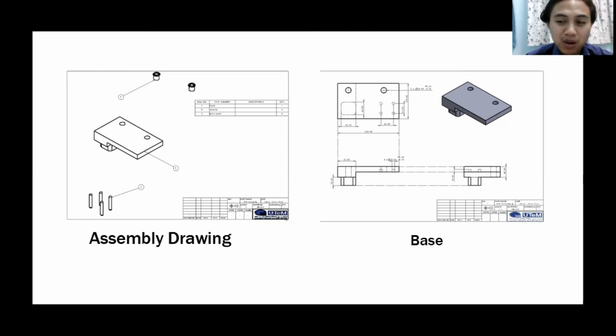This Poka-yoke concept in the design reduces or prevents errors associated with misalignment of the part. Selection of the locator allows fewer product quality rejections due to direction, when datum point tolerances along a certain plane are less strict.